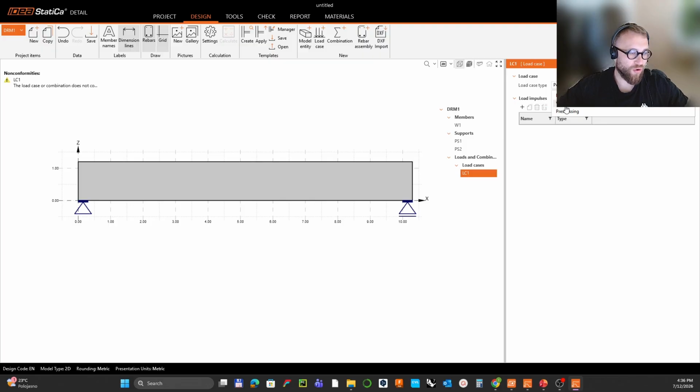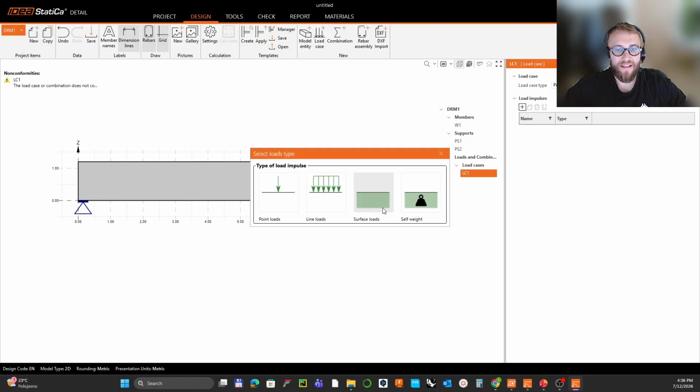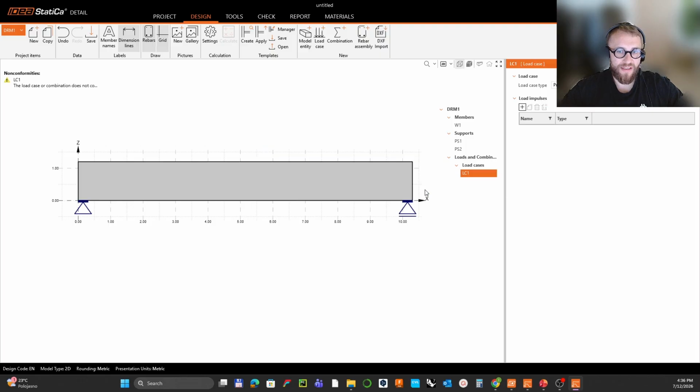It has also more consequences, but actually, if you want to add some incremental load, you will at first pre-stress it. So you will specify pre-stressing, and in the pre-stressing, once you are pre-stressing the structure, the self weight is also activated, because the self weight is working together.